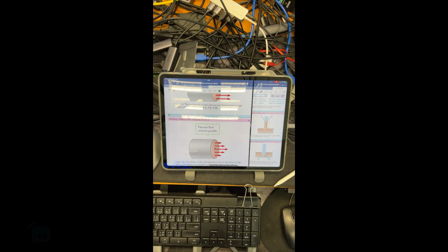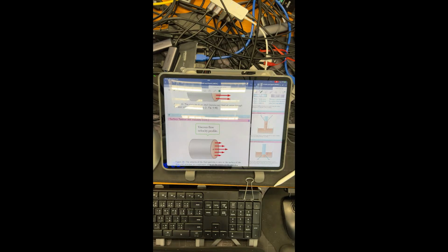When the obstruction is not strong, the water or the fluid in this position is going to move very easily, so its speed or velocity is going to be high at the center. When you are close to the center, you will have less friction, and your velocity is going to be increasing and increasing. The velocity of the fluid particles is zero at the surface. We would say it has zero movement, no movement, because the friction is very large at the surface of the pipe, and it increases to the maximum value at the center of the pipe. All right, and what else?